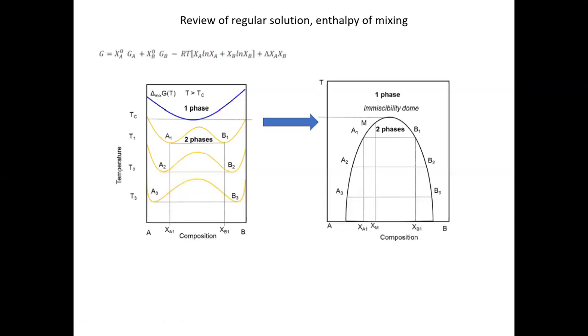Yes, so that's the entropy of mixing, the free energy of mixing. Now if we want to get the phase diagram, we have to go back to the overall free energy of the system. This is very straightforward. We just add the free energy of the mixing case as a reference, and then we have the total free energy again. We did a lot of analysis for this, and we got the chemical potential, activity, etc. But I won't go into that right now.